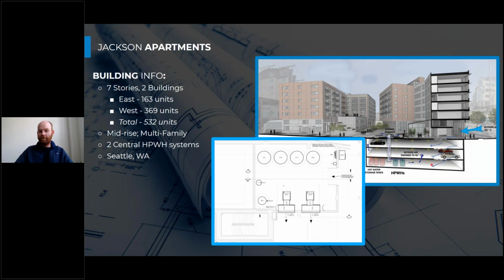And so for at least 10 years now, we've put temperature sensors in garages throughout the Seattle and Pacific Northwest region and measured those temperatures over the course of a year, or many years actually, to determine what's the lowest temperature we regularly see. And we see the outdoor air drop below 25, sometimes down to 23, even cooler recently. But in the garages, we typically don't see it drop below about 40 to 45 degrees Fahrenheit. And that's above the minimum temperature for those R134A heat pumps.